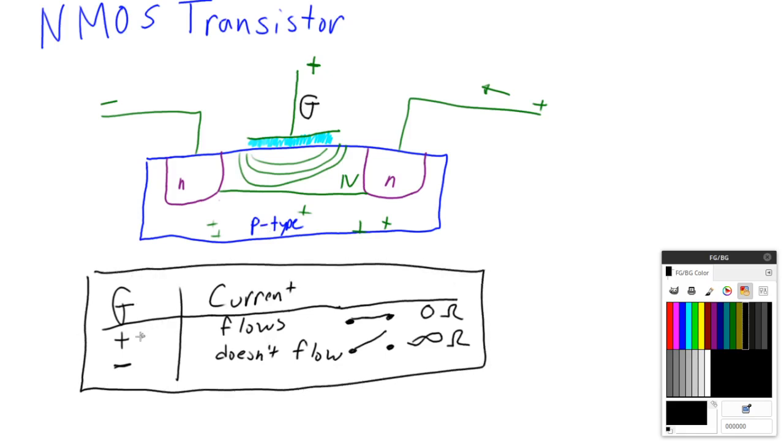In terms of digital logic, if we apply a plus here, so that could be a positive voltage, maybe like 5 volts, and then this could be 0. So I'm going to say 5 volts, and then we'll say 0 here. We get this behavior. And so our symbol for an NMOS transistor, if we want to look at our super simple symbol, it looks like this.